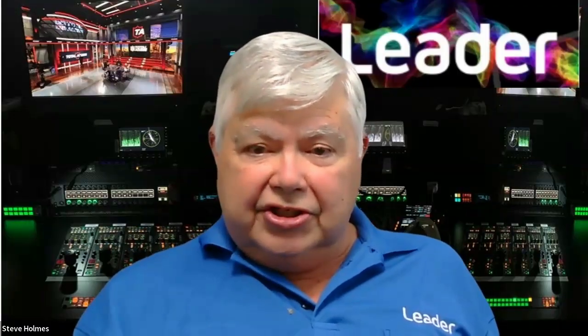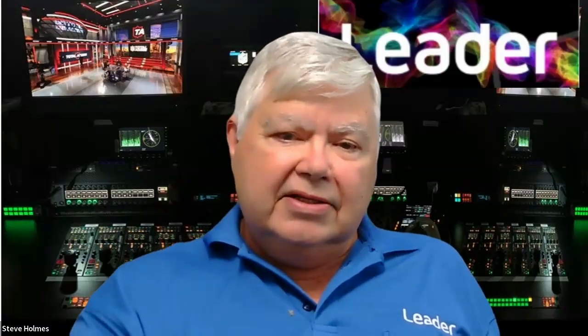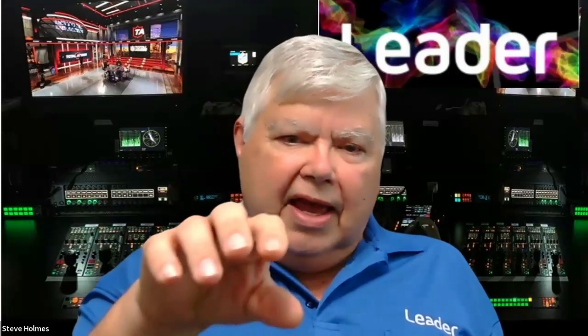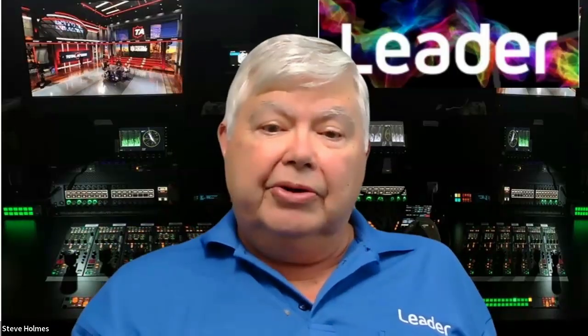So it's just sitting there waiting to come online when the BMCA says that its clock quality and priority 2 are better than the generator that is online. It's ready to go. It's listening to the announce messages, sending its announce messages to the network, and just waiting to go online as soon as it becomes better than the generator that's online.